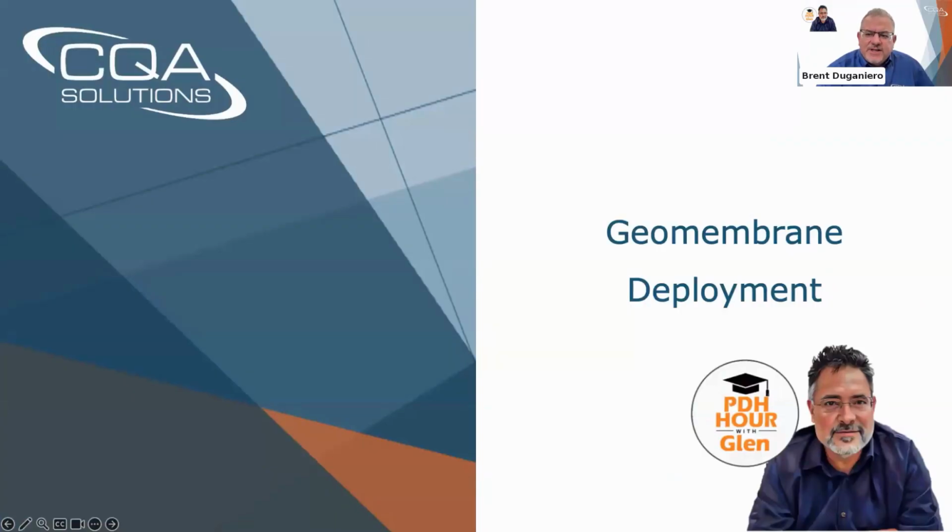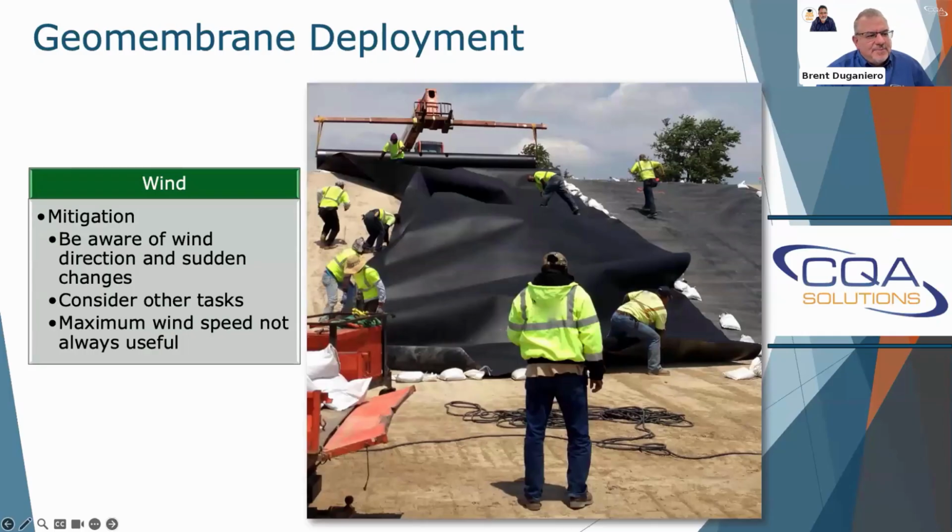Okay, so our anchor trench is excavated. Now we're deploying our geomembrane. We ought to be concerned about the wind. As we deploy longer and longer panels, sometimes 500 feet long or greater, you've got that much geomembrane pulled out and a wind picks up, somebody could wind up seriously injured, especially if that material were to come loose in a textured geomembrane. You find yourself quickly in a dangerous situation.